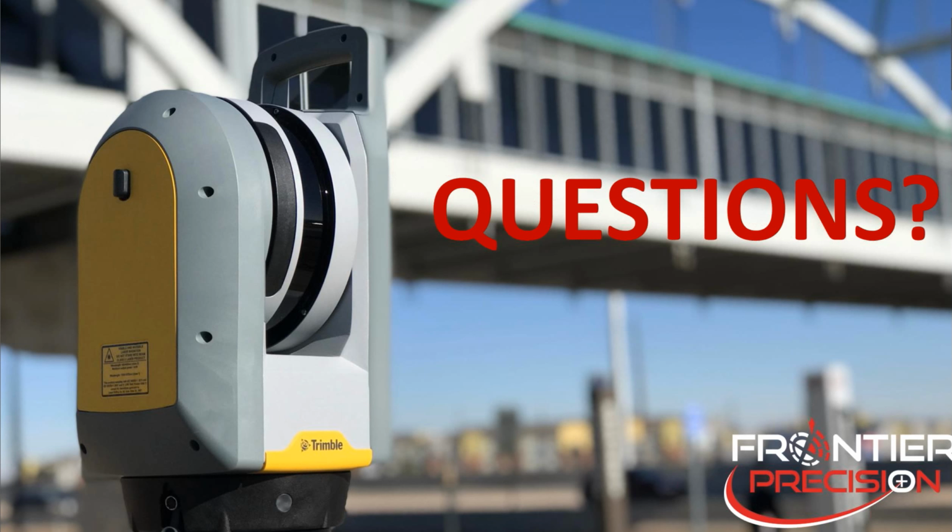Yeah, so Sean, I did see that on a lot of the buildings, pretty standard. Obviously, a lot of the focus was on the road, which for the most part looked really good. But when we started looking at some of the buildings, we definitely saw some of those weird swirls along the edges and in the point cloud, some holes in the sides of the building. Now, we only flew this as a single grid. One thing that did come up when I presented this in one other place was to fly a double grid. But even with that, I've seen some of those same things that you're talking about. It definitely didn't come into play here because we're more worried about the road, but we definitely saw that.